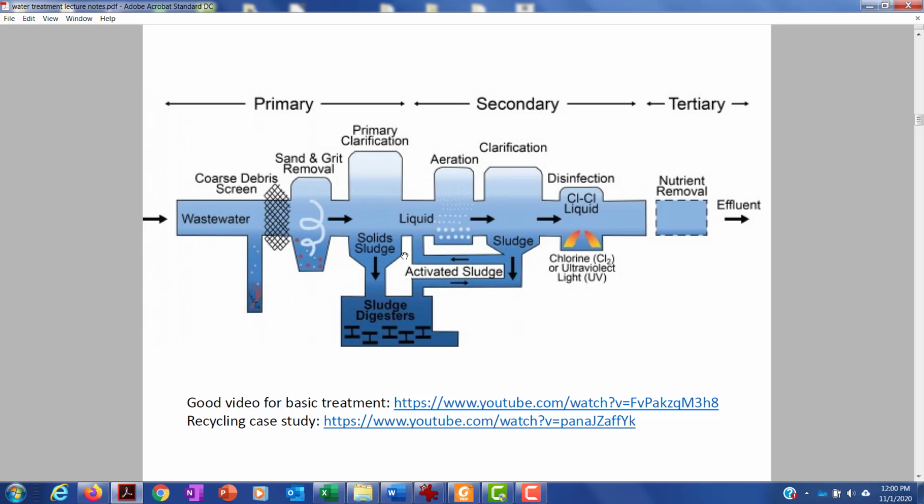I think Water 4.0 does a good job with this activated sludge business, why that's there. And we know from respiration why aeration is so important. We need to add that oxygen as the electron acceptor so that the bacteria can take the organic molecules we put in this system and respire those compounds into ultimately carbon dioxide and water.